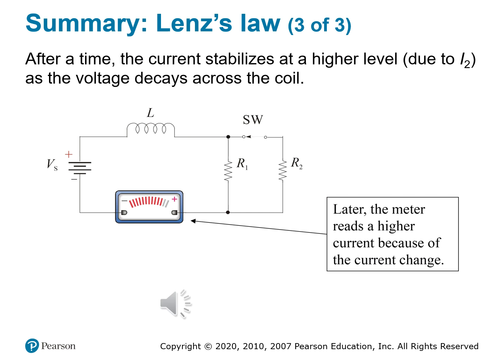So in this final diagram, the switch remains closed. The current flows through both R1 and R2. At first, the inductor again opposes the change with an induced voltage, but over time, as the current settles into a new steady state, the magnetic field becomes constant again, and when that field stops changing, the inductor no longer resists. The induced voltage across the inductor decays to zero, and it acts like a simple wire, just part of the circuit now. And what's the result? The total current increases, and the meter shows a higher reading than before the switch was closed. That's because the total resistance has decreased. The current now flows through R sub 1 and R sub 2 that are in parallel.